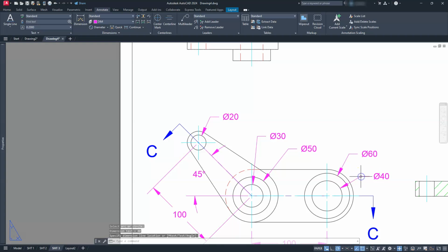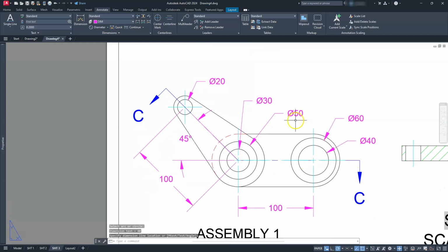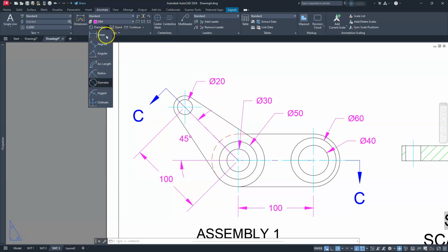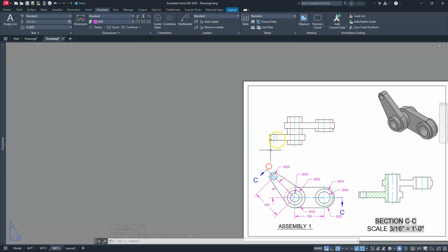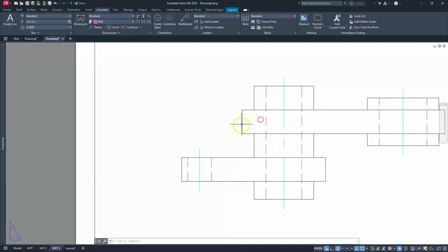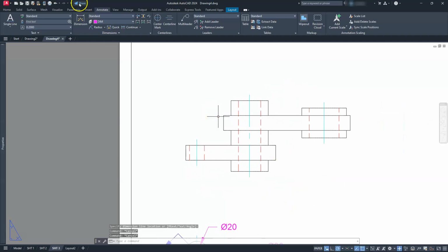If it's showing you maybe 60% of the circle, that's a good candidate for a diameter dimension, right? So I'm going to use a radius dimension on these, and you see that these are not quite whole circles here. They're just parts of it. So it's a good idea to use a radius dimension on that, and that's the rule behind which ones to use. As far as my dimensioning up here, these are all going to be linear dimensions.